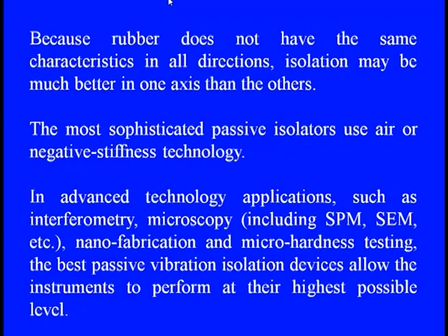of absorption of the vibrations. Because in that we need to design the passive isolator in such a way that we can use the air as the suspension device, or sometimes even the negative damping as a suspension device, along with these elastomeric features of the rubber. Through that we can effectively control the vibration for such a sophisticated system.